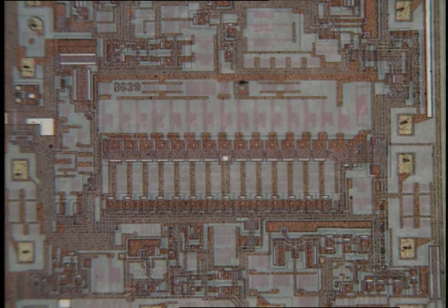Using the term translinear in its broader context, here we see an example of a highly accurate translinear network which generates the sine or cosine of an input with an unusually large angular range of plus and minus 500 degrees. By incorporating two such networks on this chip, all trigonometric functions and many of their inverses, such as the arctangent, and some less common functions, such as the versine, can be generated using just pin strapping to alter the function.